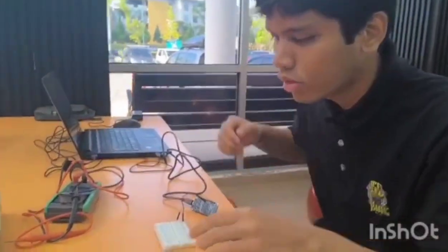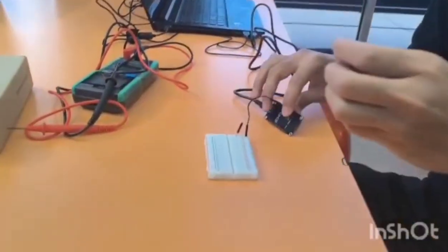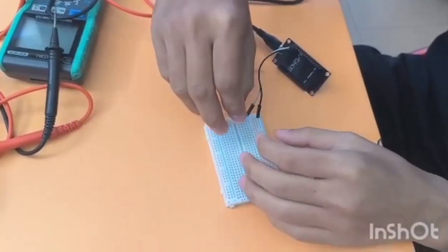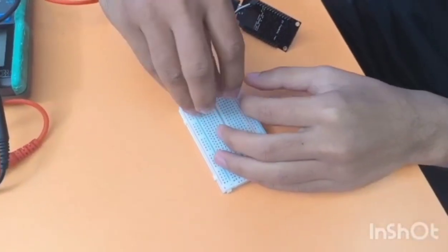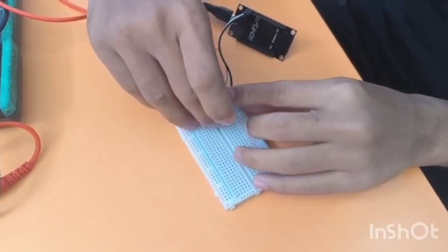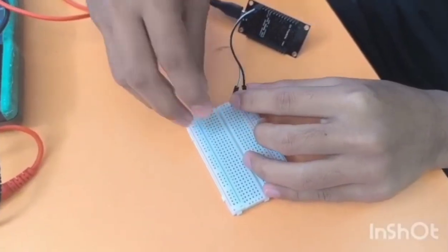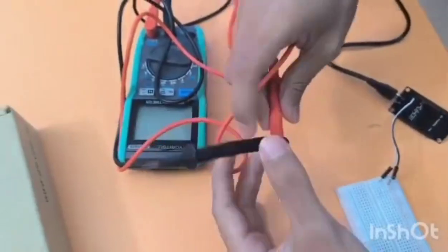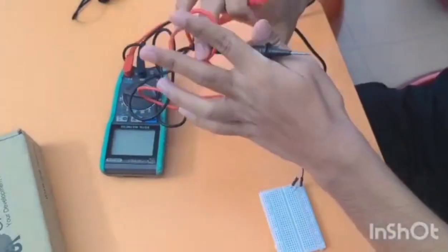Today I will explain how we can measure current for DC voltage. First of all, we must have a resistor and the power supply. The negative terminal must connect to the negative terminal, while the other terminal is not connected to the positive because we want to measure the current. Current is equal in a series circuit, while not equal in a parallel circuit.